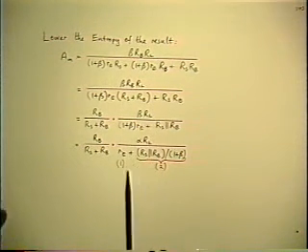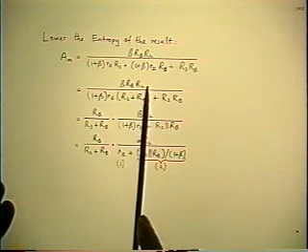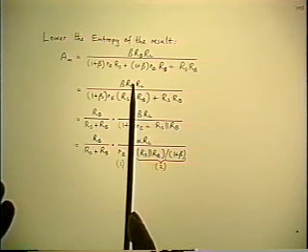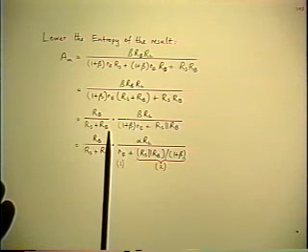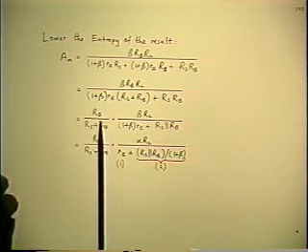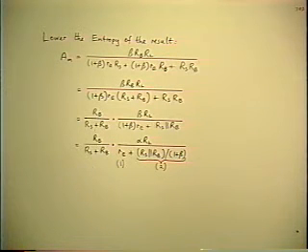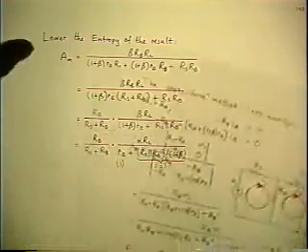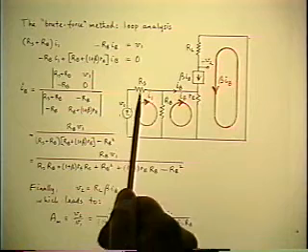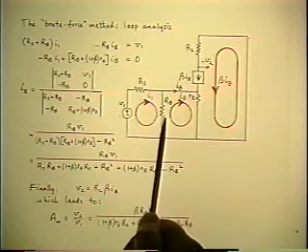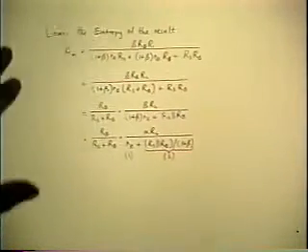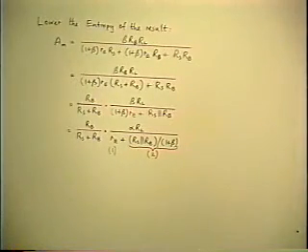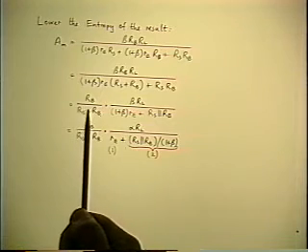Having done that, you can see that if we have an RB in the numerator as well, if we bring out RB from the numerator and RS plus RB from the denominator, we get a ratio of resistances which has a direct physical interpretation, because that is the resistive divider that the source looks into. RB over RS plus RB is simply a divider ratio whose physical origin is obvious from the circuit. So it's a convenient factor to have in front.